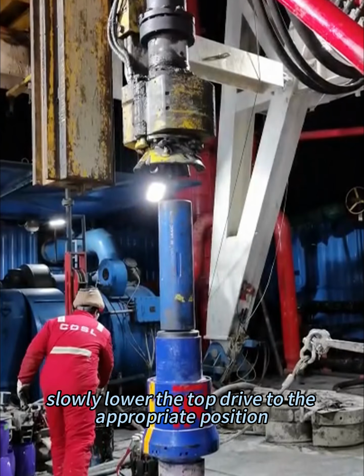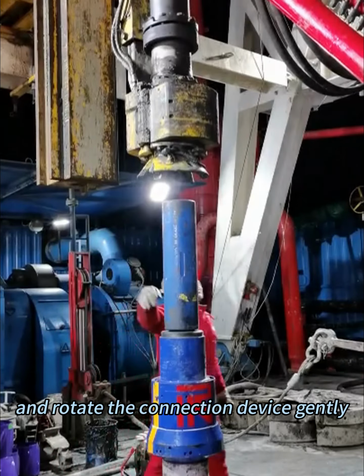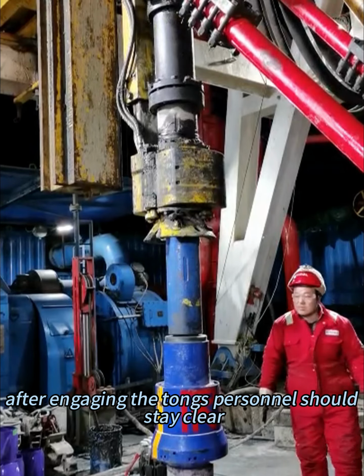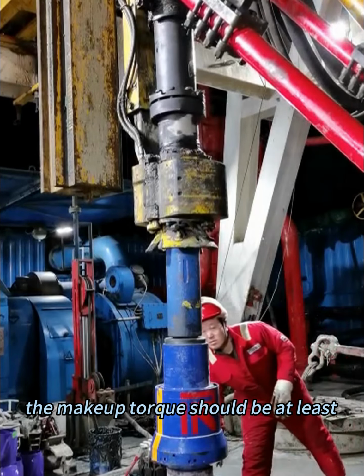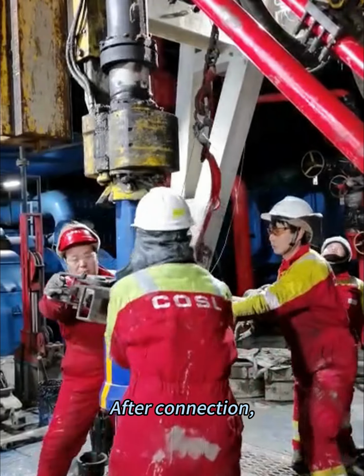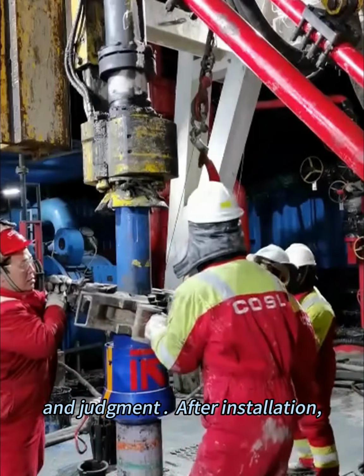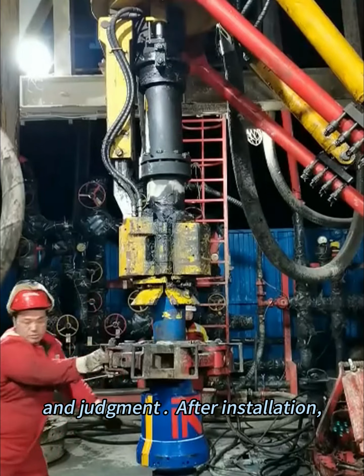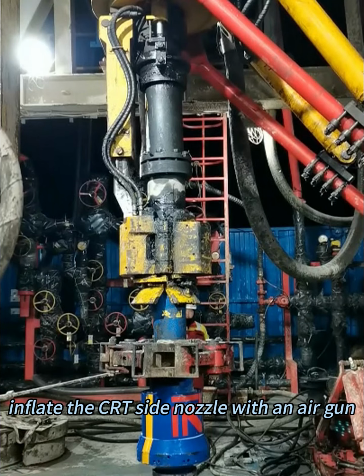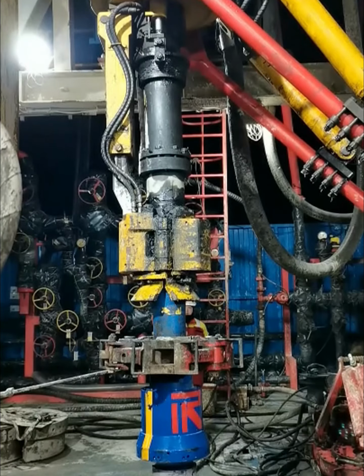Slowly lower the top drive to the appropriate position and rotate the connection device gently. Use manual tongs to grip the locking sleeve with the CRTi. After engaging the tongs, personnel should stay clear. The makeup torque should be at least 1.25 times the required casing torque. After connection, spray an identification line on the joint for daily inspection and judgment. After installation, inflate the CRTi center nozzle with an air gun, typically to 0.6 to 0.8 megapascals.